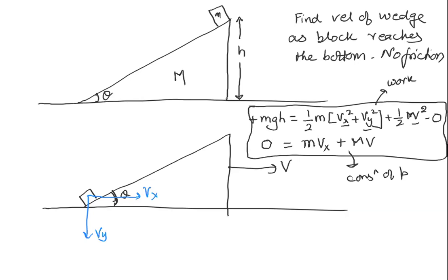So the constraints in this must be that the velocity components in this direction, perpendicular to the interacting surfaces, must be equal. Okay? So मैं यहाँ पे ये v बना लेता हूँ और ये Vx और Vy के कंपोनेंट्स निकाल देते हैं. तो ये लाइन नॉर्मल रिएक्शन की लाइन है, तो ये वर्टिकल से वही एंगल बनाएगी जो वेज का एंगल है. ये एंगल 90 माइनस थीटा हो जाएगा और ये एंगल 90 माइनस थीटा हो जाएगा.